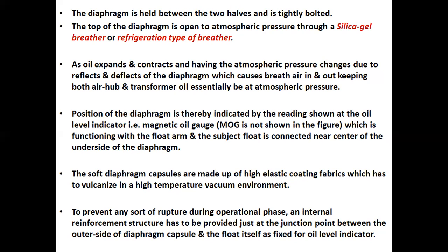An internal reinforcement structure has to be provided just at the junction point between the outer side of the diaphragm capsule and the float itself as fixed for oil level indicator. That is, one reinforcement structure is required at the junction point of the connection of the float with diaphragm.